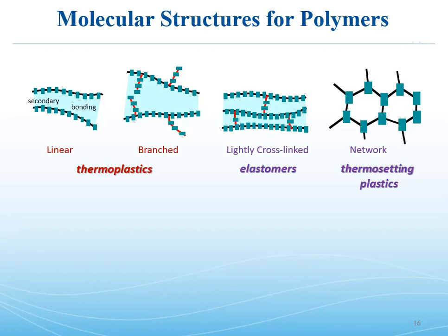If we go sort of in the direction of more order, more strength, more association between chains, we can drop a few covalent bonds across the main chains, like we discussed with cross-linking. That is a cross-linked polymer. This is used very frequently with elastomers to keep them from creeping. If you are familiar with the action of O-rings, how we need to maintain a certain squeeze under a footprint, creep is definitely not your friend, and so cross-linking will prevent that. It's very valuable. But of course, if those cross-links are full-up covalent bonds, no recycling. You can't repurpose the polymer just by melting or softening.